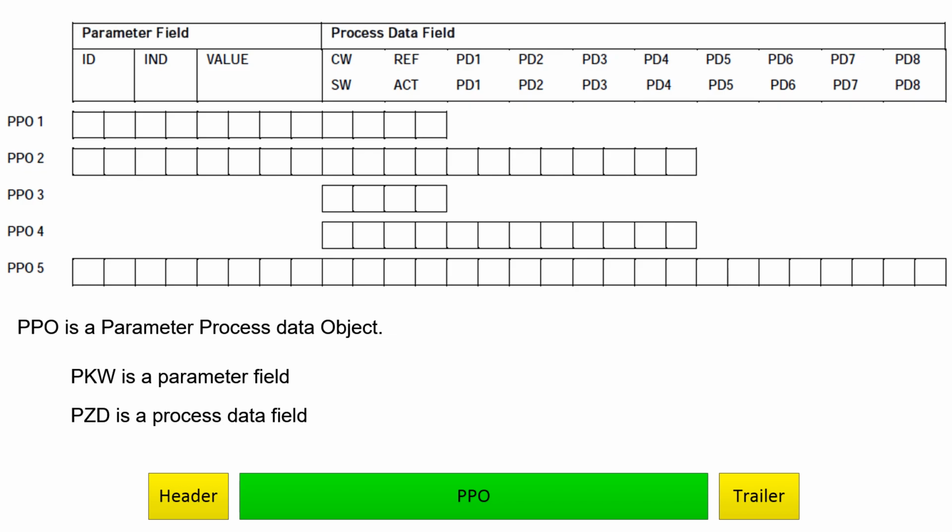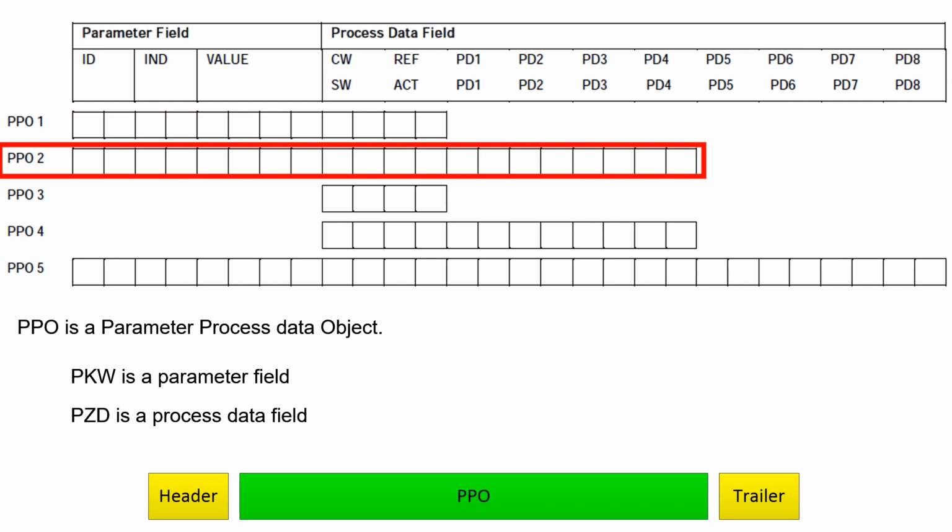How to pick up the right PPO that would suit your needs? Well, let's look up at the matrix of the PPOs. By choosing PPO1 you will be able to monitor and change the parameters of the VFD. Also, you will be able to send main commands to the VFD and get feedback from it. PPO2 will allow you to do the same as PPO1. In addition you will be able to monitor additional 4 values.